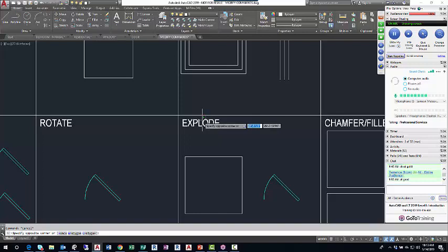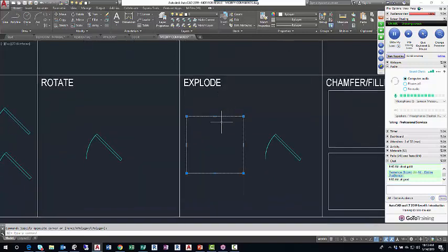There's explode right there. There's a rectangle or a polyline in the explode area and a block reference, or most AutoCAD users would just say block. I can left click the rectangle, left click explode, and it just simplified this rectangle. Now it's 4 lines. With the block reference or block, if I left click this and click explode, it changes the color of that block.